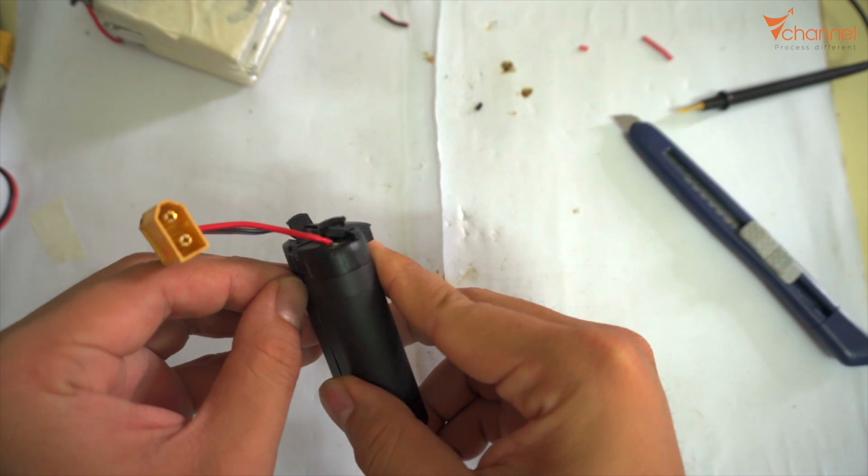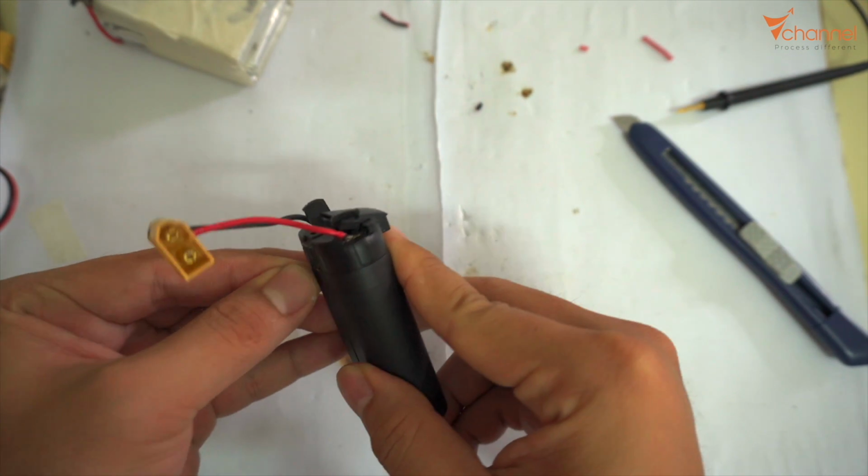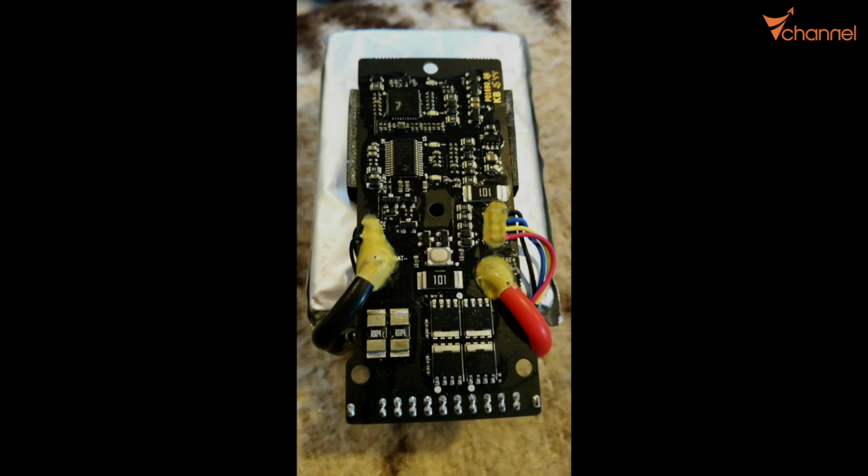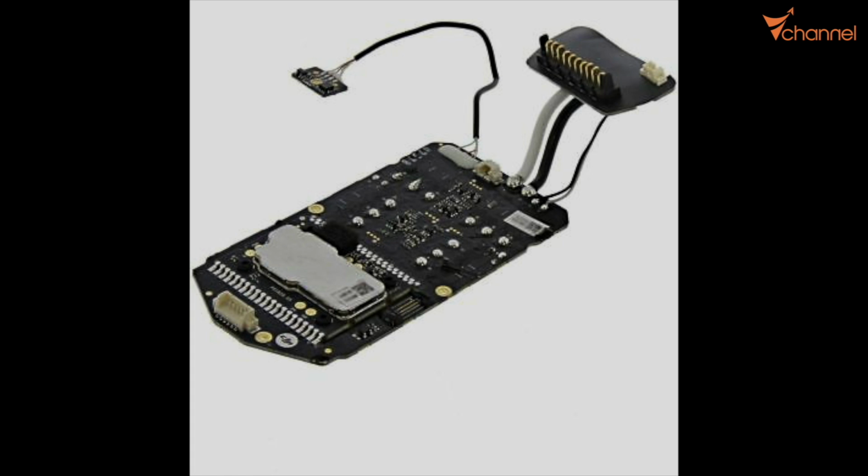In case the battery cell is too old or damaged, you can use this method to change the new battery cell. In general, the modifying for Mavic Mini is easy because the Mavic Mini battery has no lock circuit at all, so we can replace it easily with the higher capacity product from Mavic Pro. When the lock circuit realizes it has lost the power supply current, when you remove the original cell, the lock chip will lock immediately. So that case is more difficult than Mavic Mini.